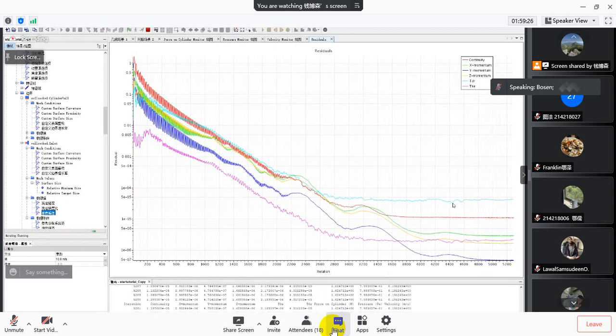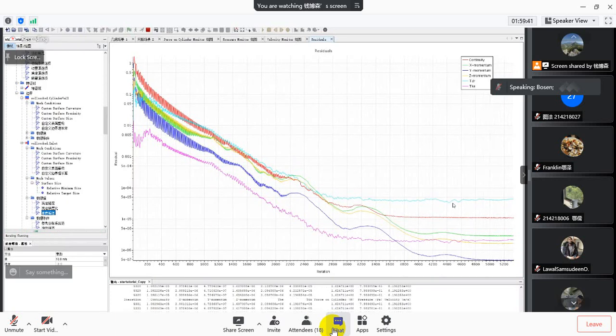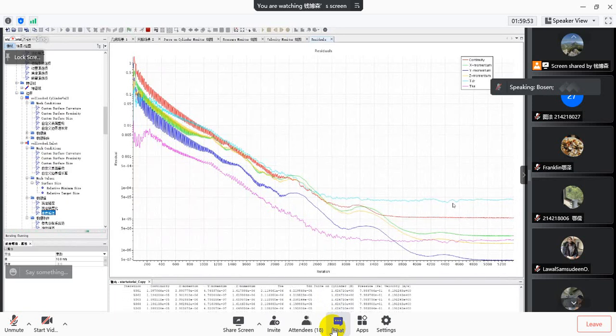For train aerodynamical study, unlike the flow around the cylinder, which is a very, very simple case, we might have an extremely complicated geometry and very, very poor quality mesh. So that will all lead to the decrease of convergence level.